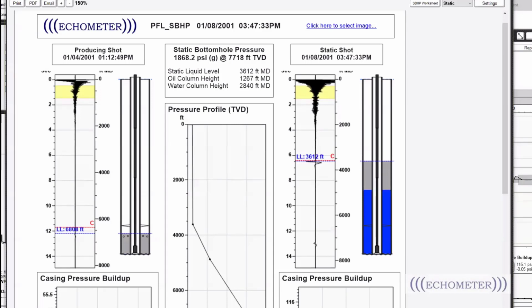answer for that. Another question from Sam Barkey says, how do you find out the production interval? I'm not sure that I get the question, but the production interval is an input that you need to get before you shoot the fluid level. And where do you expect to calculate the pressures on? They would have to come up with that from their wellbore schematic or perforating records. But definitely it's an input that you need to find out as part of the well information that you need to run the fluid level tests.